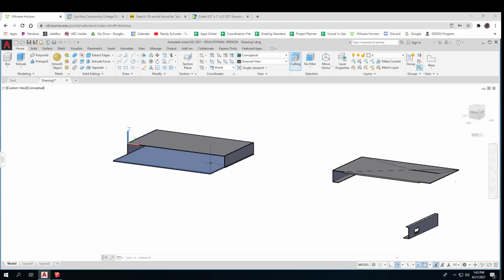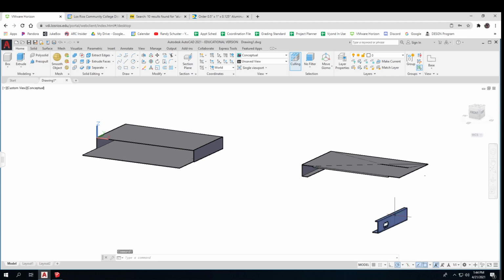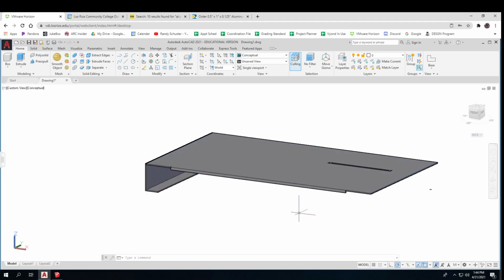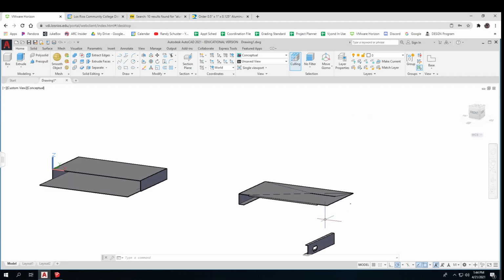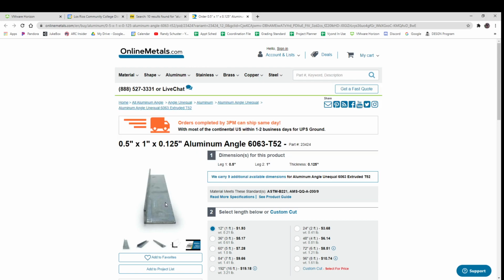You can say, this is my basic shape, and one way I want to put it together might be this. Another way might be all one piece. I need to maybe stiffen it a little bit. Here's one way. I could stiffen it just by welding one of these pieces onto the back side of it. Very, very easy just to weld those on.